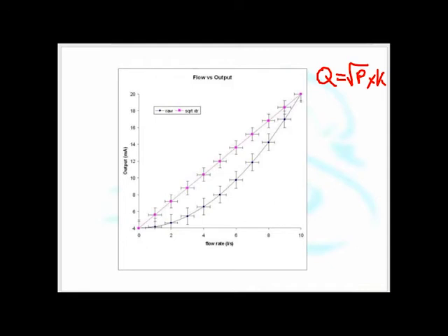When we set up our flow meter, there's a value which is normally called linearization. When we're setting up a pressure sensor to be a flow meter, we need to select square root linearization. If we select linear linearization, we'll get the wrong values.